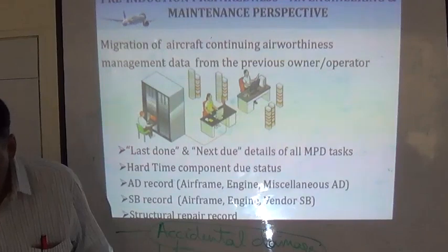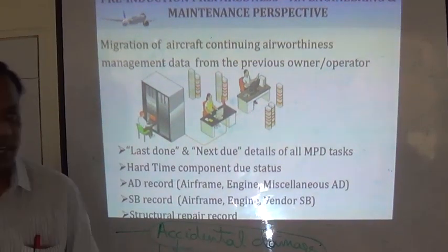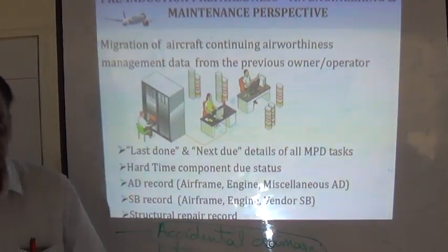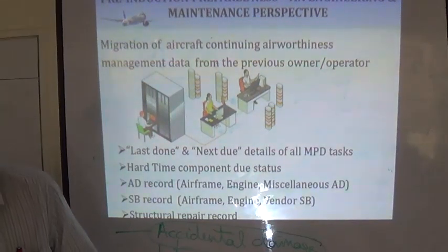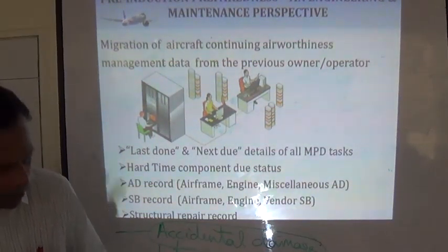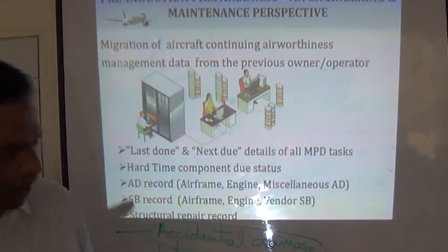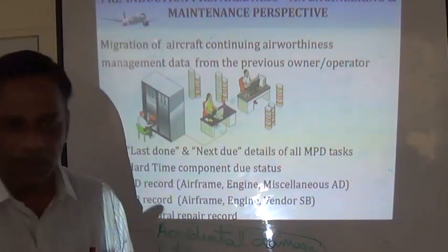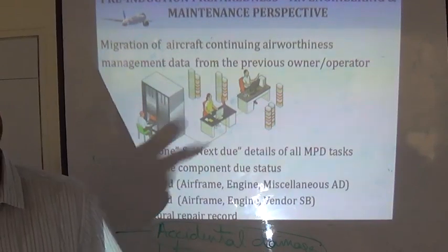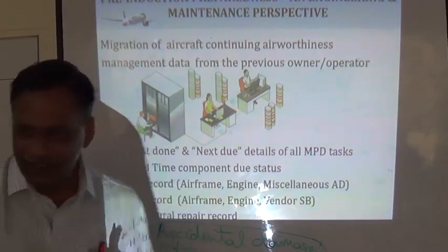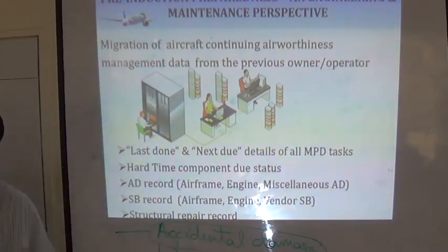So after every sector, when the cleaning people come and fill it up, some dripping happens and some waste water goes down. So when you go for inspections, MRO checks, or when you're doing an MRO check in the operating base, you will see a lot of corrosion. So these are all corrosive environmental damages.